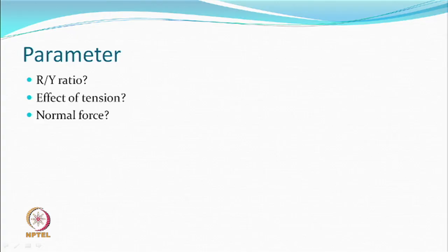Otherwise, you will again have a situation of dragging or pumping. So, the best situation will be where both the tensions are equal. Their magnitude would change depending upon the draw ratios that you set up. Here also the tension is not providing the normal force.